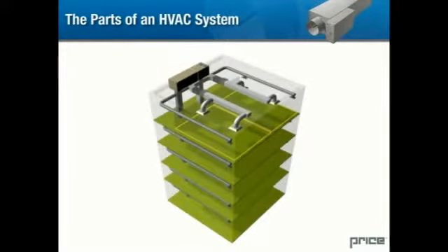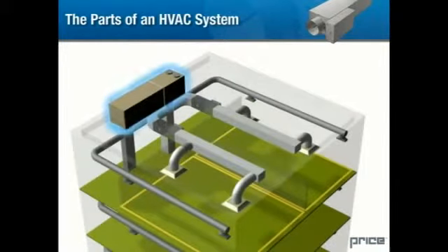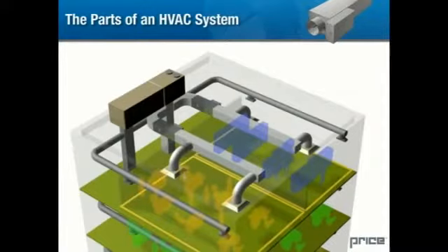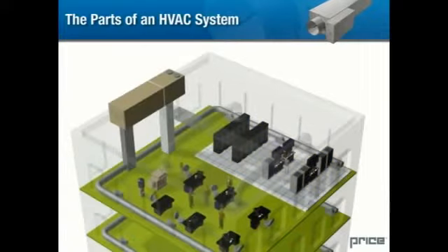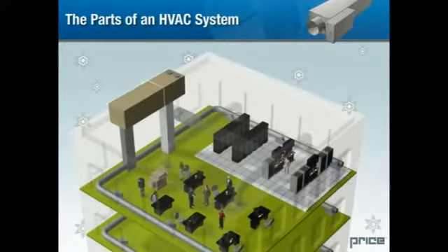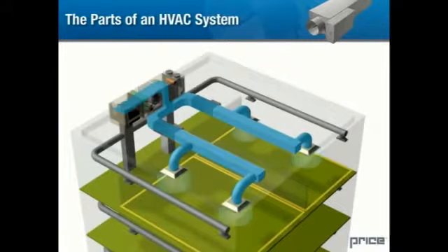The conditions in an office or commercial space are quite different. Higher concentrations of people and equipment will generate more heat, making air conditioning or recirculation of air more important than providing heat. Although the air handling equipment is centralized, different rooms and regions in the building will have different needs for heating and cooling. These needs are called loads because they place a load or demand on the HVAC system. These loads can come from equipment, people, weather, and many other factors. In the simplest case, we address this by providing a constant supply of cool air, which is then managed by the HVAC distribution system.